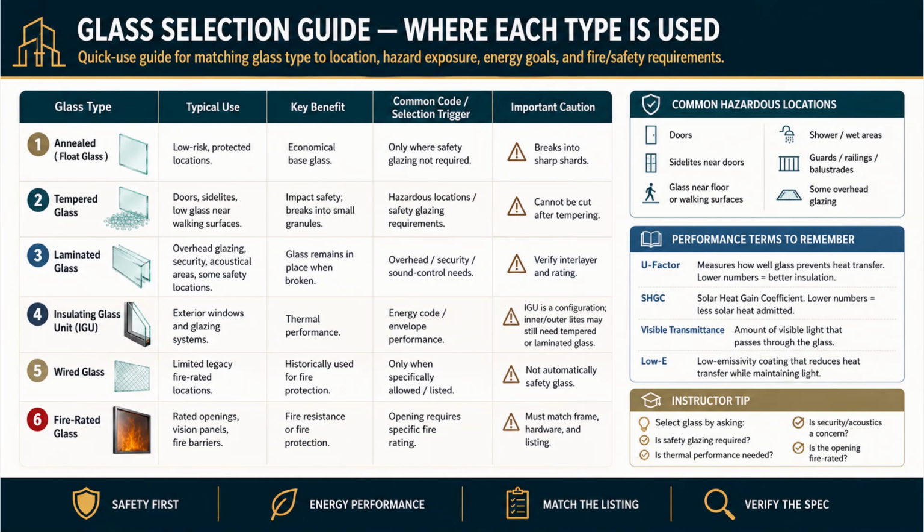The instructor tip frames the whole selection as 4 questions. Is safety glazing required? Is thermal performance needed? Is security or acoustics a concern? Is the opening fire rated? Answer those 4, and the glass selects itself.